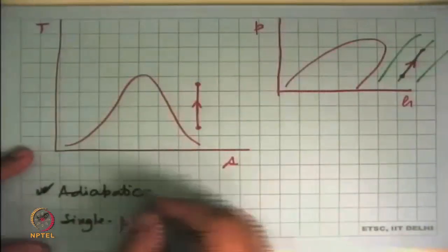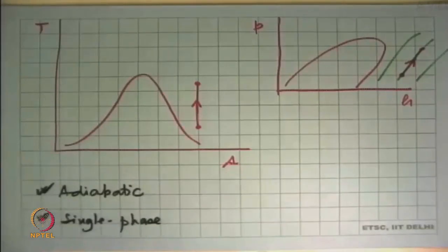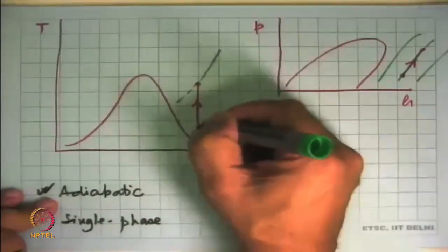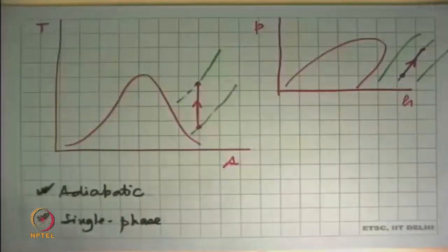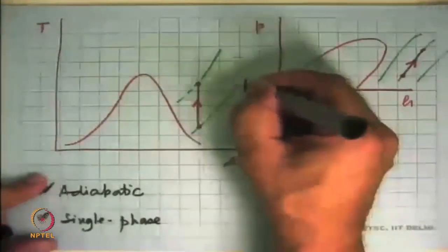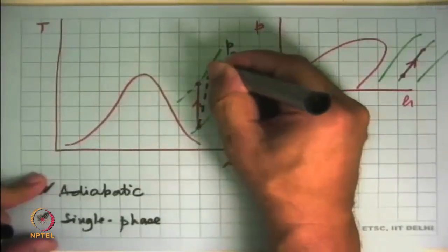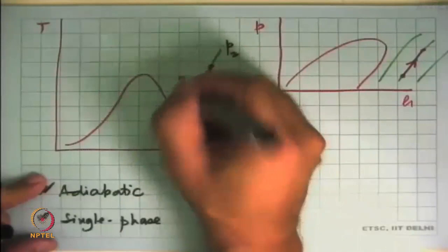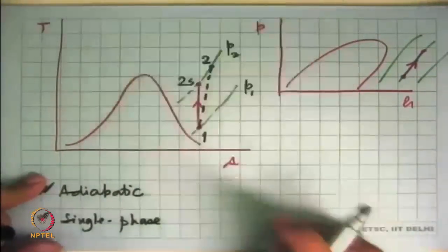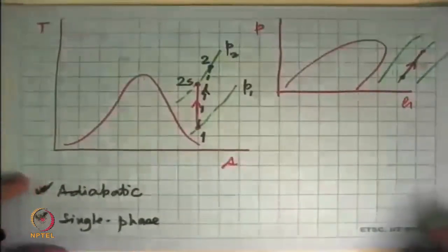Now if it was not a reversible process and we say it goes to the same final pressure, in this case the constant pressure lines are here and here. So the inlet pressure is assumed to be constant, the discharge pressure is also the same, so this was P1, this was P2, and then the non-isentropic compressor would do that. So this we will denote as 1 to 2s, s means isentropic, and 1 to 2, this is the real case. A dotted line because the process is irreversible.